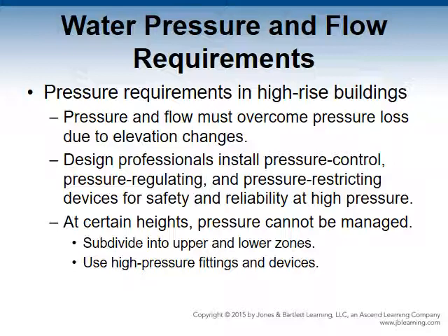Systems are subdivided into upper and lower zones. Water supply for zones may come from numerous sources. The need for pressure control is minimized by zoning the systems and using high-pressure fittings and devices, all depending on which floor and setting they're in.